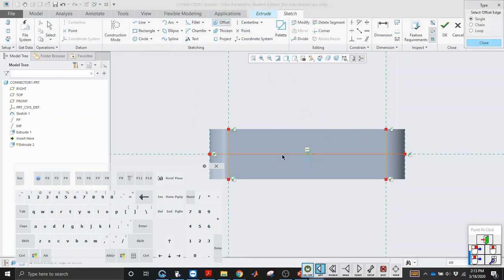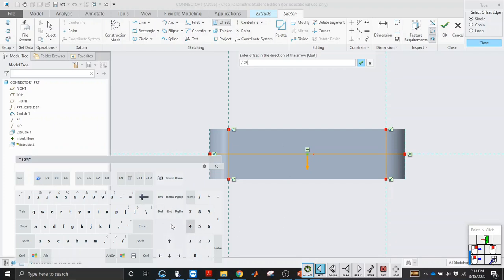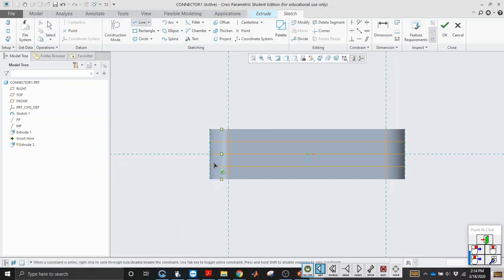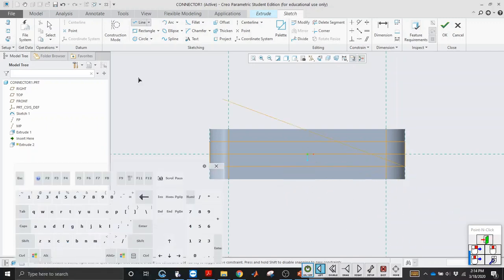All right. My favorite offset tool. Our coupler was 1/4 inch thick, so let's make this a 1/4 inch slot. Minus 0.125. All right. Obviously, if you don't want to watch this part of the video, you can just fast forward to where I actually get done assembling. Let's get rid of you.